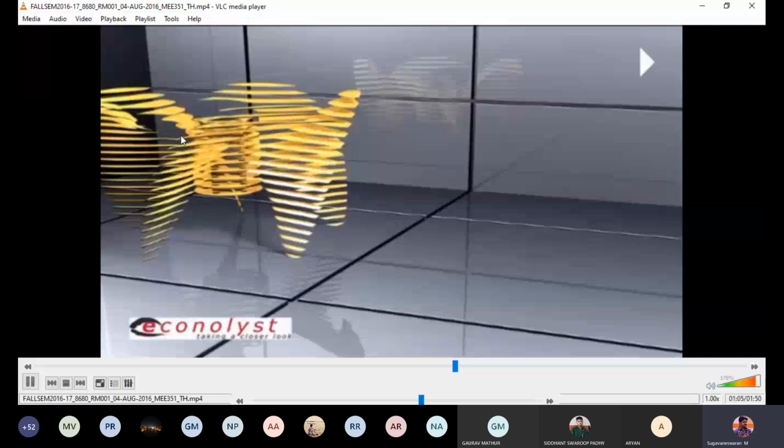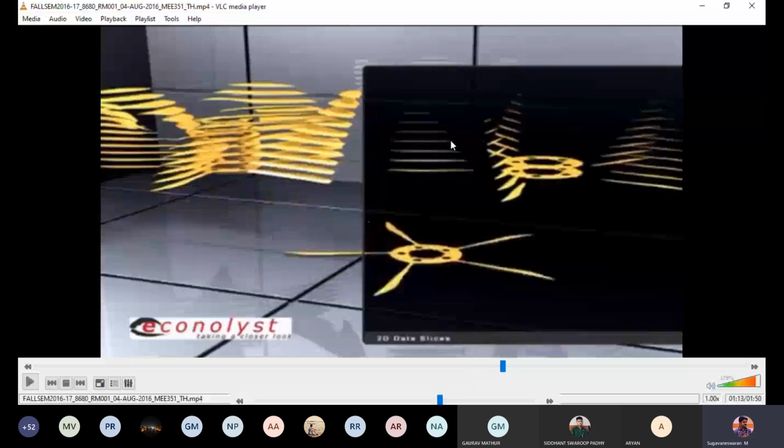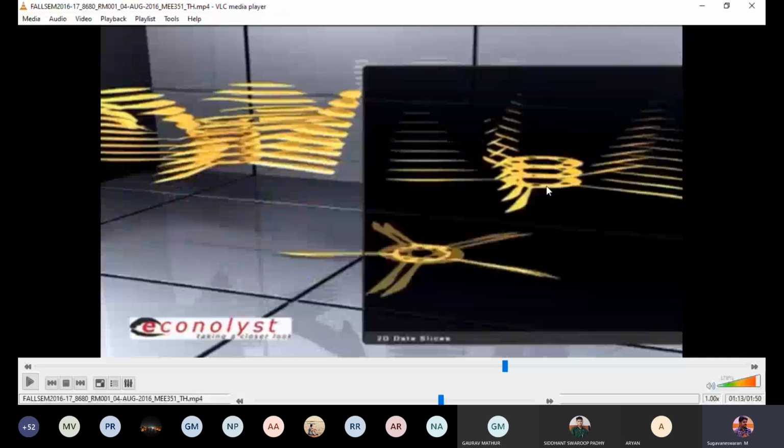Each 2D layer represents the profile of a physical layer, which will be made using the additive layer manufacturing system. This data will be sent to the machine layer by layer. You can see each and every slice is a flat face, which has a predefined contour in the X and Y axes. In the Z axis, there is no variation. But when you stack all of this, you will get a variable profile along the Z axis, and that becomes a three-dimensional component. Once all the layers have been sliced, they're then stored as slice files on the additive layer manufacturing system, waiting to be used. For each slice, you have to define a path in which you are going to deposit the material. That is the sixth step.